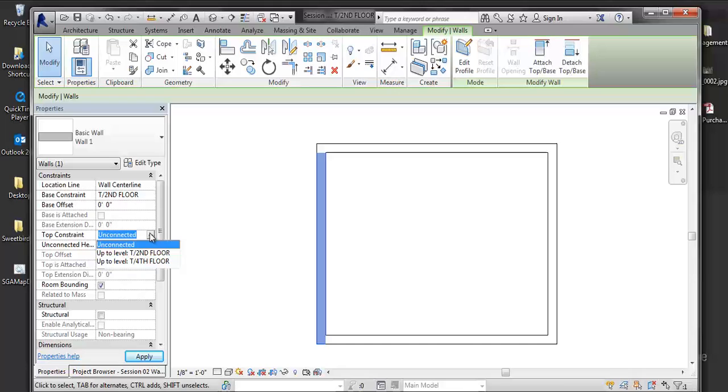And then if I go to copy my walls up from level to level, you'll run into issues. Like if I move a floor or I need to change the level height and everything's constrained, all of a sudden you get a bunch of warnings later down the way. So just be aware that you can pigeonhole yourself sometimes by connecting them. There are advantages and disadvantages at any point for this.